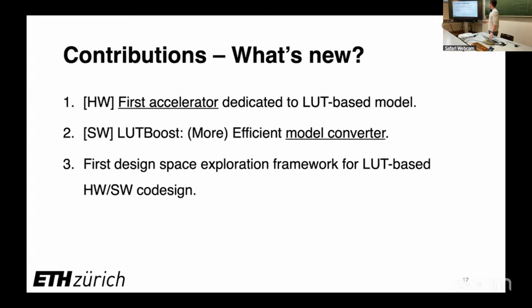The contributions, there's 2 or 3 parts. Hardware, it's the first accelerator that is based on lookup table. And for the software, they didn't invent the idea of a lookup table model, but they provide a much better way to convert that is faster and higher accuracy. And then if you're reading the paper from an implementation point of view, they also provide a useful design space exploration framework to do hardware software co-design, but I won't talk about it for time reasons.